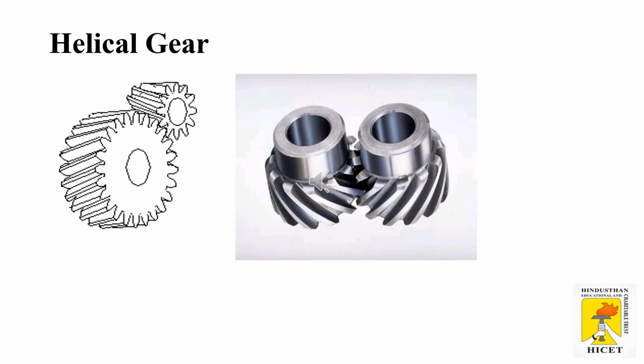Helical gears have teeth inclined to the axis of rotation and are used for transmitting motion between two parallel shafts. Helical gears operate smoother and quieter than spur gears because of gradual engagement of teeth during meshing and increased contact ratio. For the same width, the teeth of helical gears are longer than spur gears. Hence, helical gears have greater load carrying capacity.